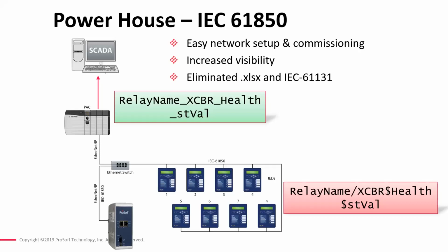There's a question about the maximum number of relays that you can connect to a client. On the Ethernet IP version of the module, we support a maximum of 20 relays. On the Modbus TCP/IP version of the module, we support a maximum of 45 relays. Ethernet IP is a more strenuous protocol from a hardware perspective and requires a lot more resources, so we just had to support fewer devices on the Ethernet IP version.